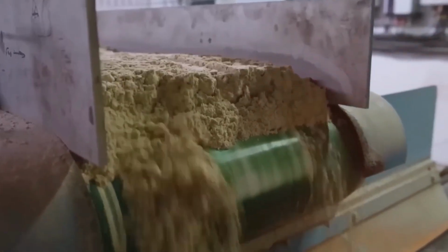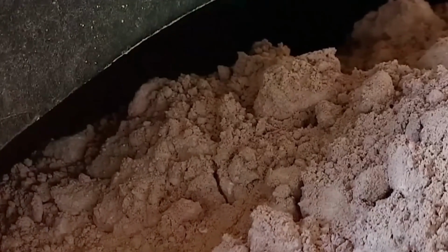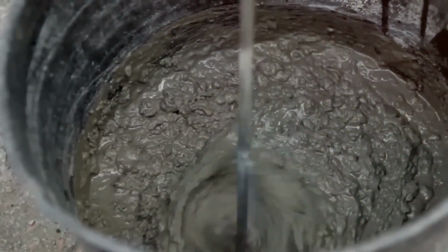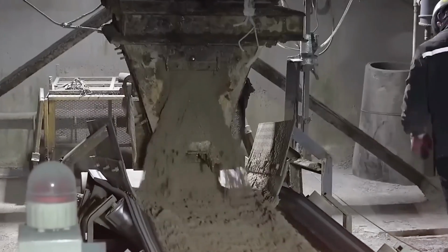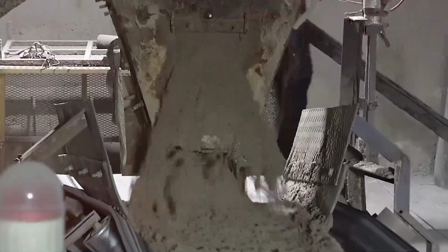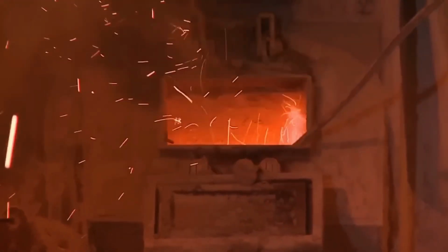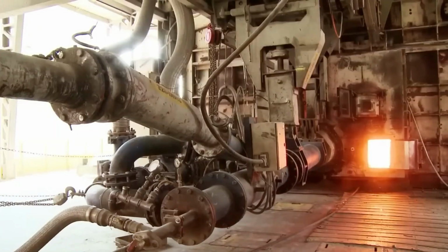This raw material then undergoes refinement in a mill, a rotating cylinder that grinds the raw materials into a fine powder. This crucial milling process not only contributes to the effectiveness of subsequent chemical reactions, but also ensures a uniform composition of the raw materials. The fine powder of the raw material is then subjected to heat in a preheated tower. Hot gases from the furnace are used to increase the temperature, leading to partial calcination. This phase involves the decomposition of carbonates in the limestone, resulting in the formation of calcium oxide, lime.